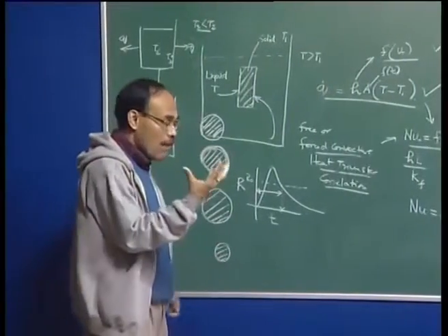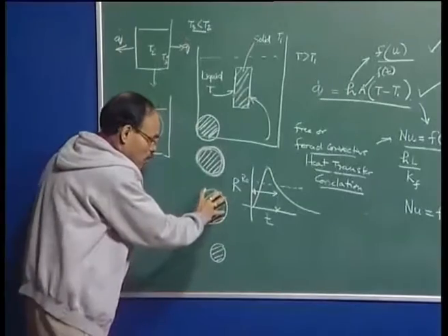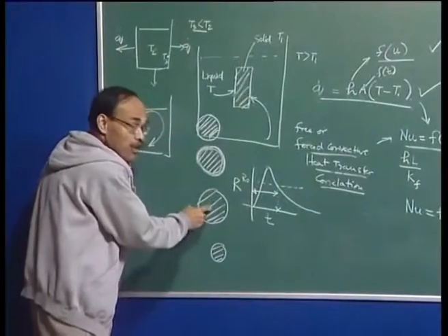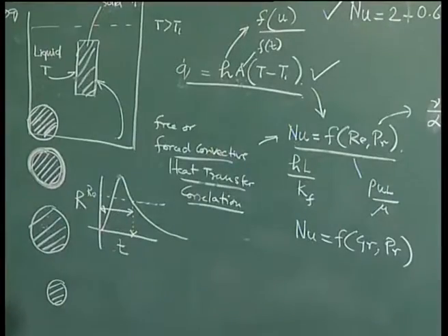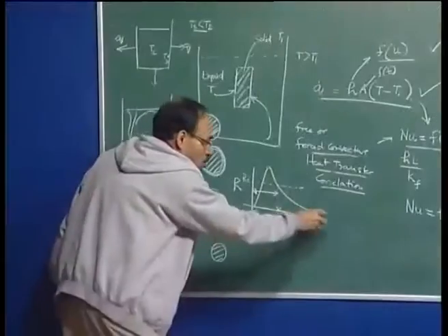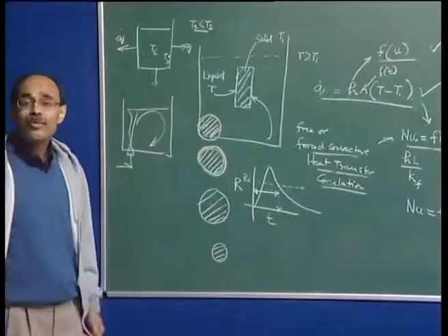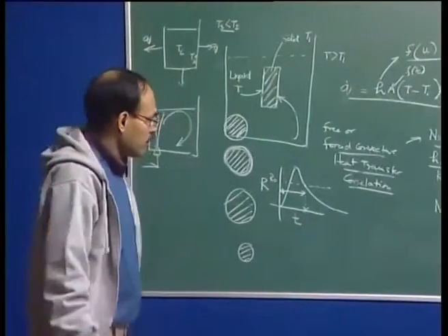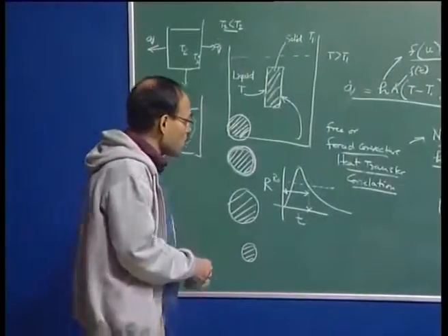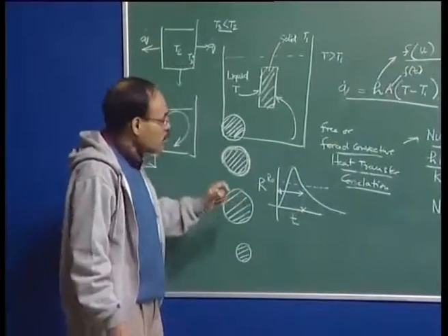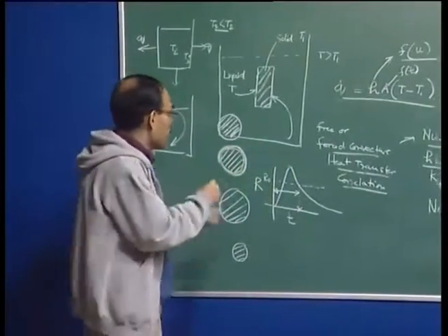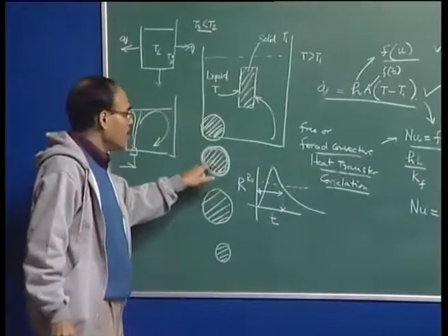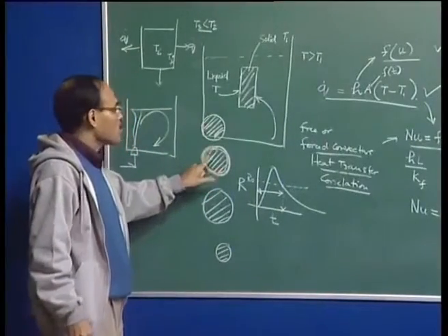then the boundary or the domain in which you are interested changes, because you want to find out the complete melting time of this particular addition. So, you want to find out the rate at which it is shrinking, and therefore, the entire time duration has to be taken into account in order to predict that time realistically. So, we have to now take into account that, for example, if I say that I want to write down the equation, the heat flow equation within the solid.